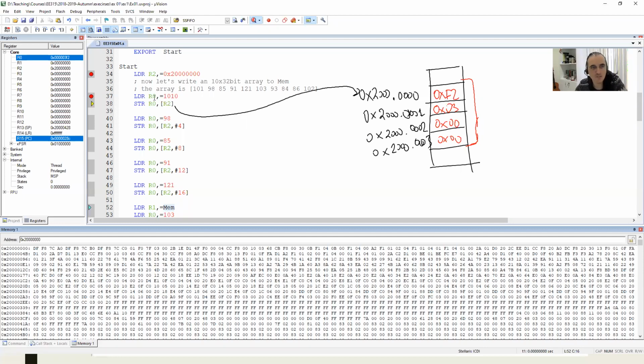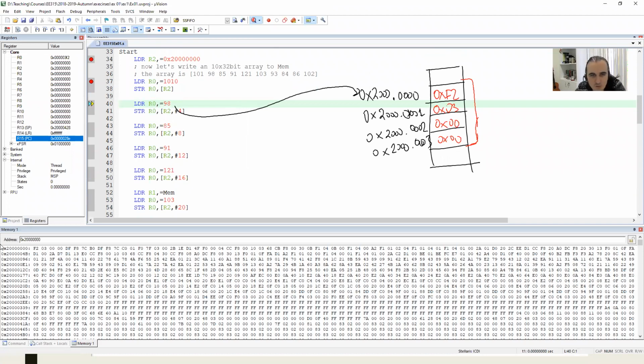So guys, if I press 10, I'm expecting that little endianness will work. And I'm going to be writing this value here. I'm writing F10. As you can see, at 20 million, I have this byte. At 20 million 1, I have this byte. At 20 million 2, I have this byte, zeros. And 20 million 3, I have zeros. Okay? This is how you view the memory.